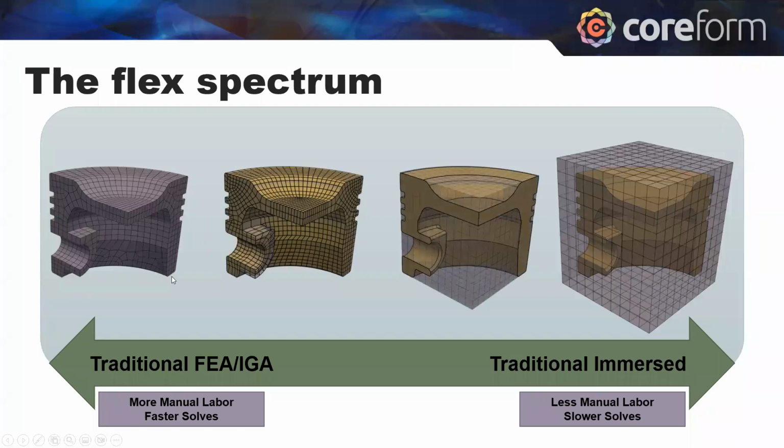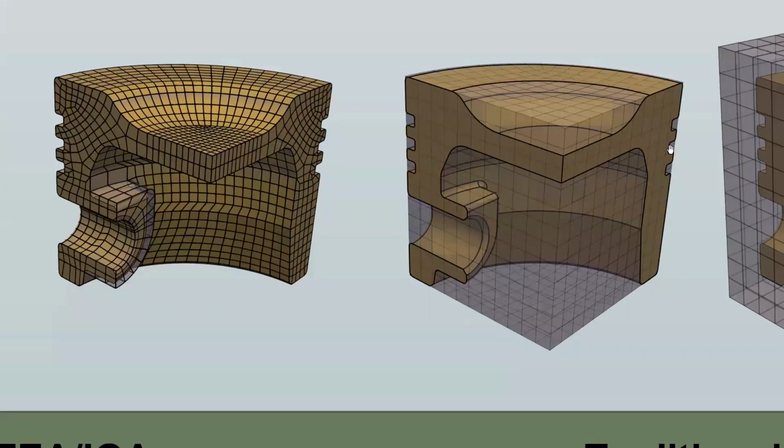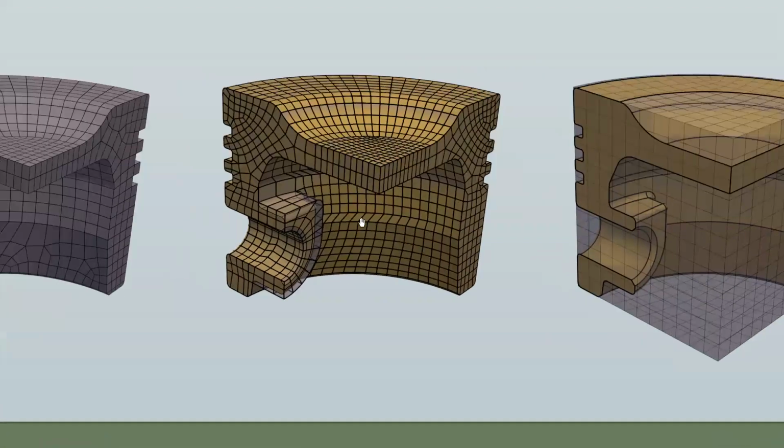But then again, with this locally immersed paradigm we can say, maybe for efficiency purposes I want to be boundary fit to the outer radius of this piston, or maybe the only region that was hard to mesh was these two shoulder fillets. So I can just locally immerse them and be body fit everywhere else. And then it's really fast to build the mesh, but still very efficient because the amount of immersion is minimal.